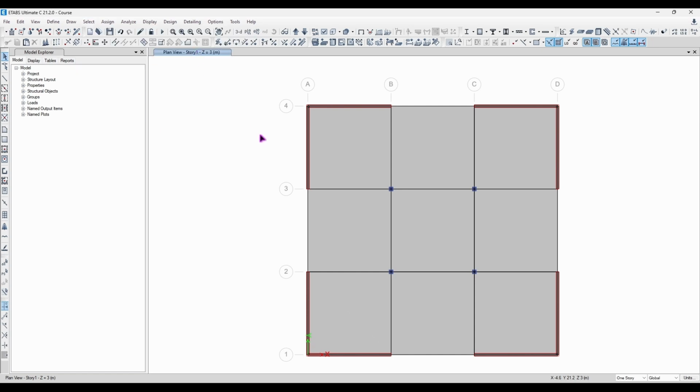Now, intersecting poly, which is going to be anything that intersects with the line of the polygon, is going to be selected as well. So anything inside or anything intersecting with the line. Now, onto the other one, which is line intersection. It's technically anything that just intersects with the line. So these were inside, but they were not intersecting with the line, so they're not going to be chosen.